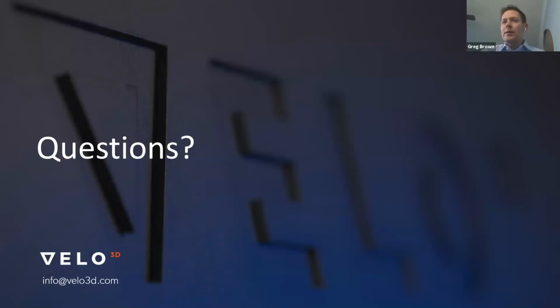Basically the height mapper was homegrown, or home developed at VELO, to be able to capture the Z height information using techniques that are kind of out there in terms of how you can do it. But what we end up getting is XY resolution on the order of about 100 microns, but the Z resolution is very accurate, so it can be on the micron level. And that's how we can determine exactly where the part is relative to the nearby powder bed.